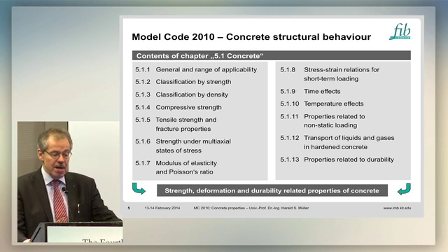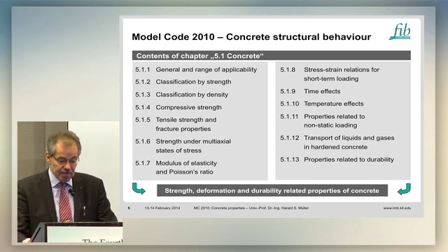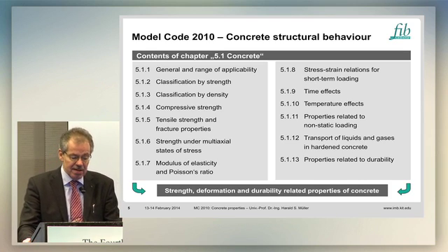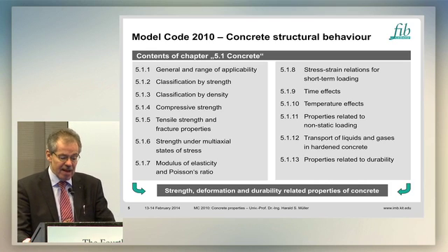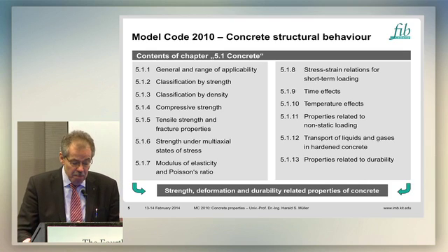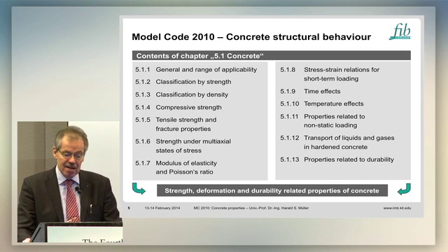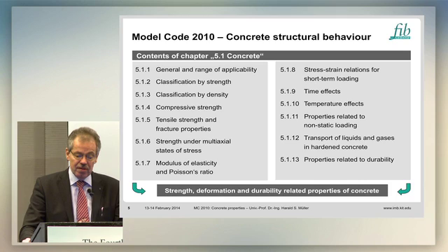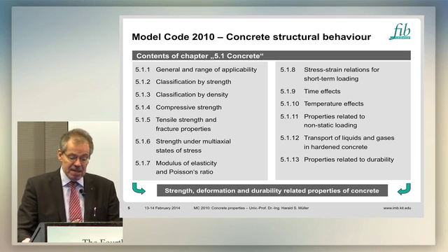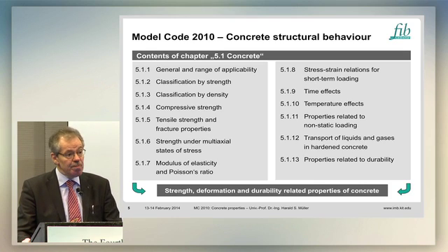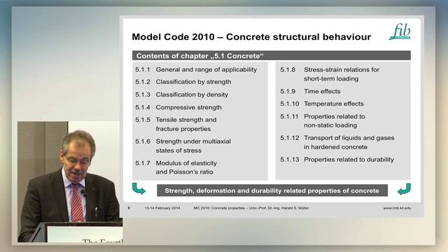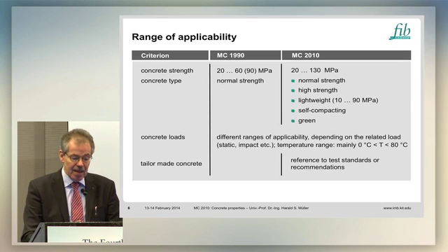You will see that it starts with some general information, then the classifications by strength and density, then it deals with compressive strengths, tensile strengths, multiaxial states of stress, then deformation, meaning modulus of elasticity, then the stress-strain relations for short-term loading, time effects, temperature effects, properties for non-static loading, then the transport of liquid and gases in hardened concrete, and also properties related to durability.